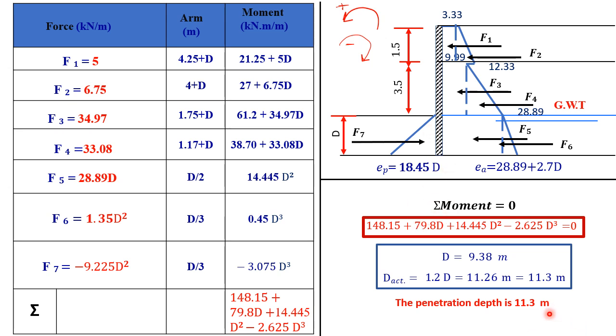So you see here the penetration depth exceeds twice your free length, or twice your excavation depth, and that's because the statical system here is cantilever retaining wall. In cantilever sheet piles you will get a high penetration depth because that's where you get your resistance, that's where you get your stability. And of course, if you have a weaker soil or a higher live load, you will get a higher penetration depth.